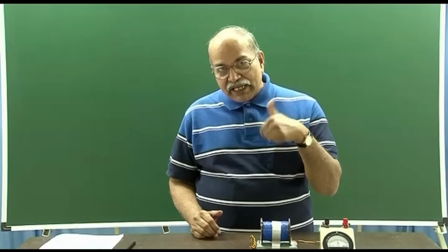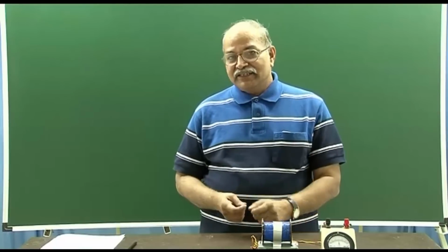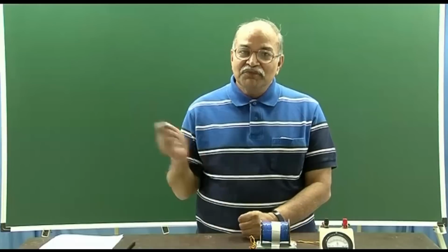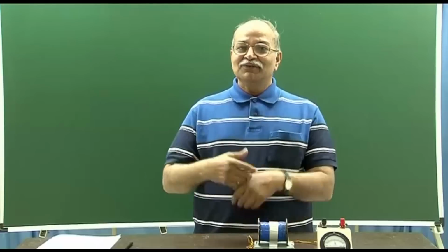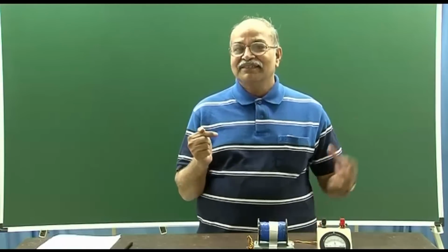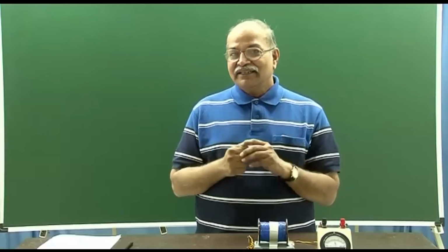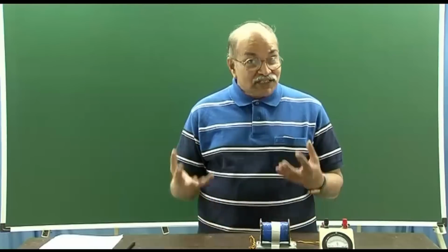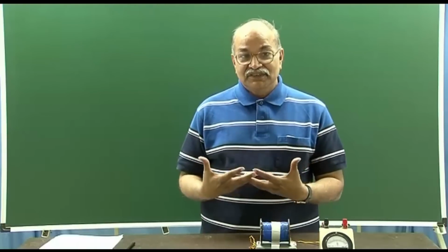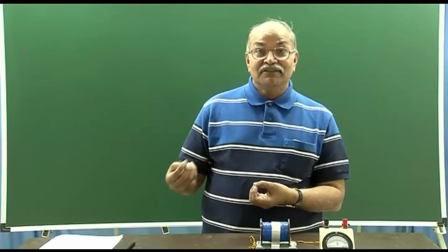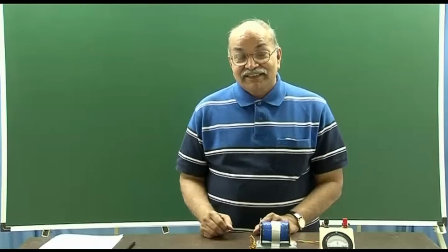You take a coil and connect it to a galvanometer, then take a magnet, move the magnet through the coil and you see the galvanometer deflecting, or keep the magnet fixed and move the coil near it and again you see that the galvanometer deflects.